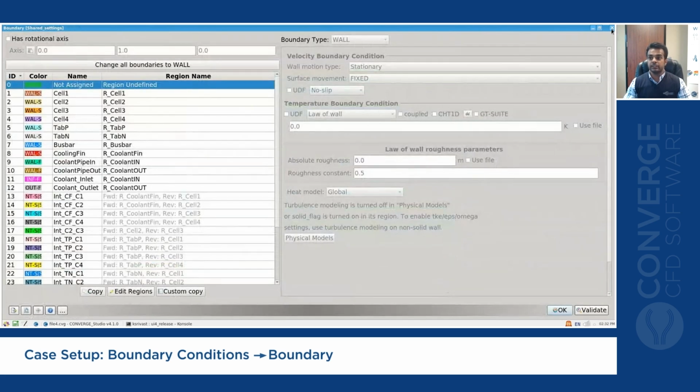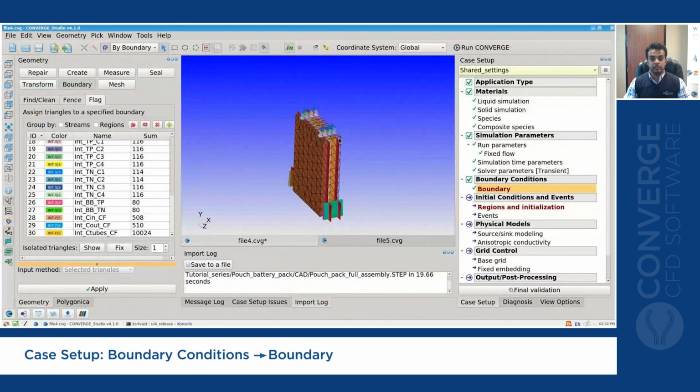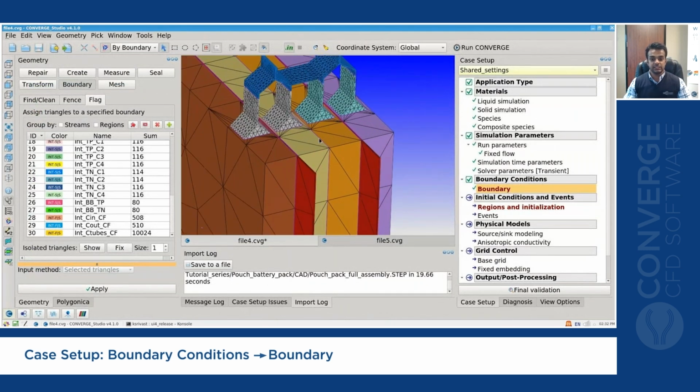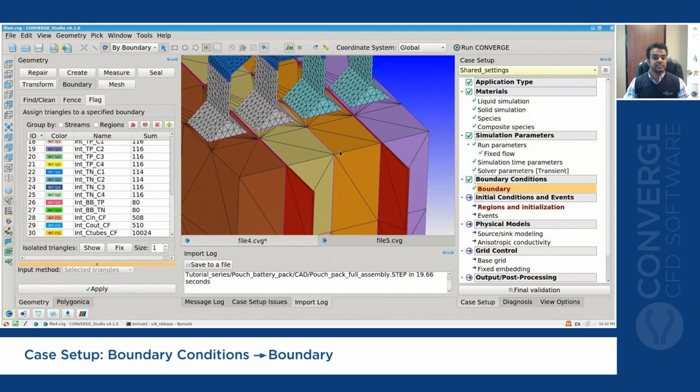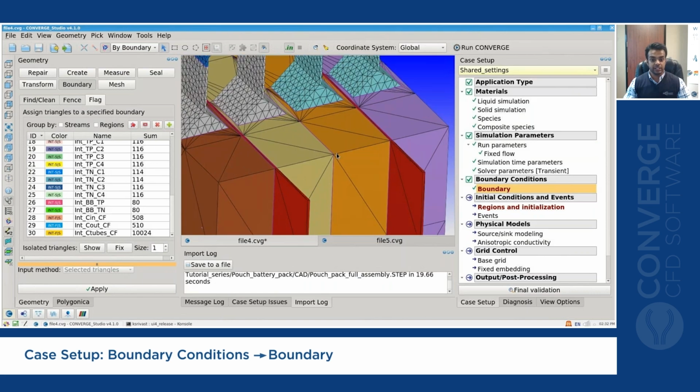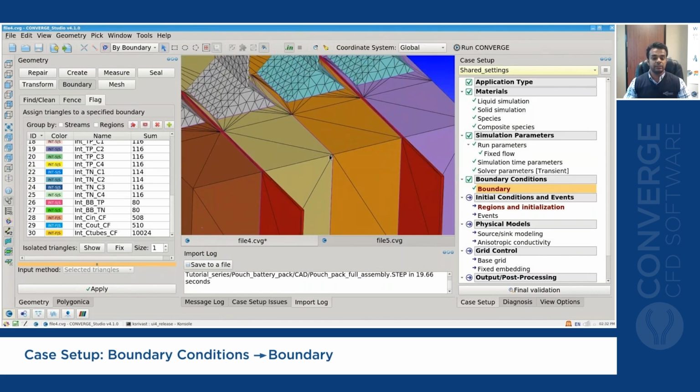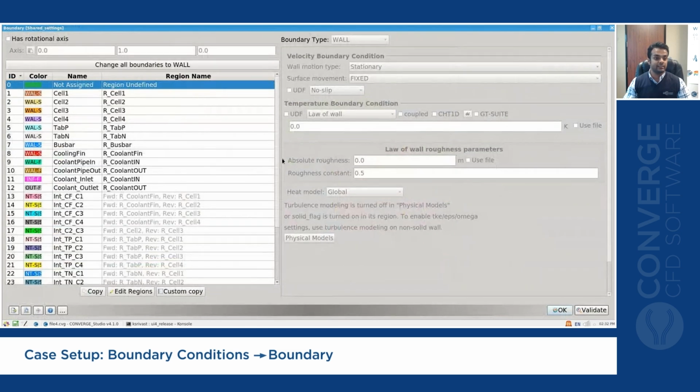One final thing for this particular problem. Between these two cells, cell 2 and cell 3, there was actually a thermal insulation material that we did not include in the geometry since it was very thin and it's not really necessary to model a thin thermal insulating material. But we can mimic the effect of an insulating material between two cells by adding it as a contact resistance.